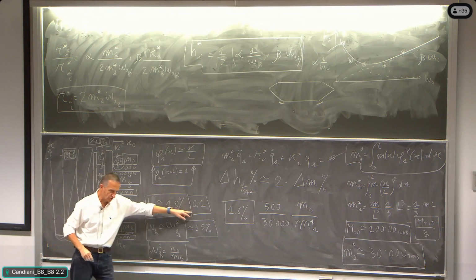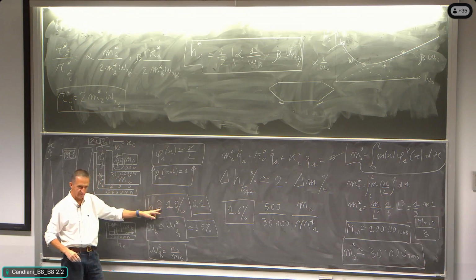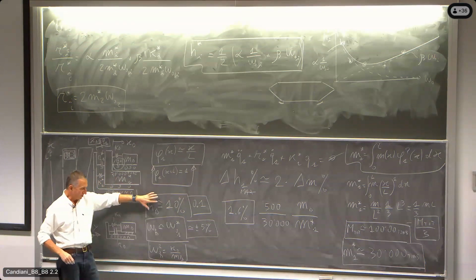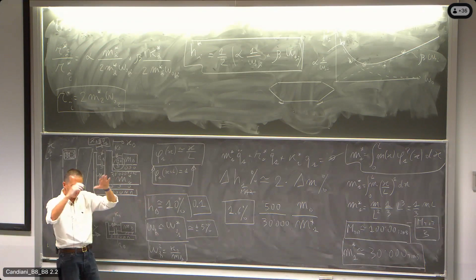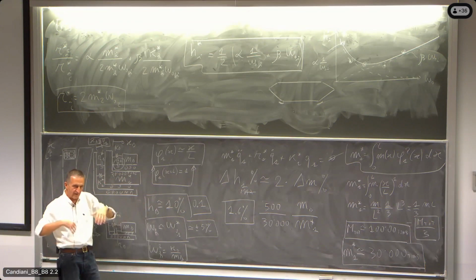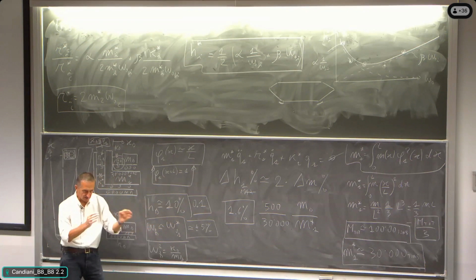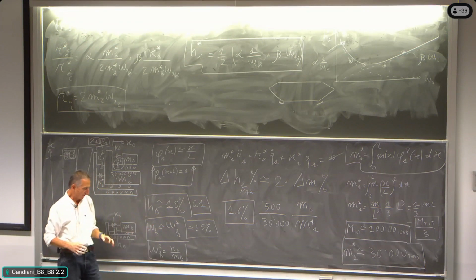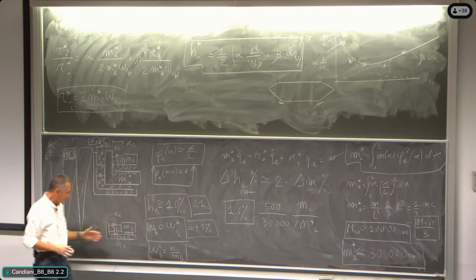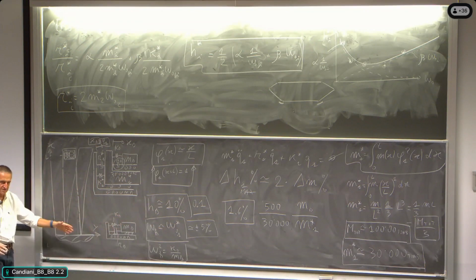Damper 0.1, that is 10%. Under the hypothesis, so the top that we can get is the best tuning in this range, some percent out of the frequency that we want to protect. Intrinsic damping of the damper, 10%.